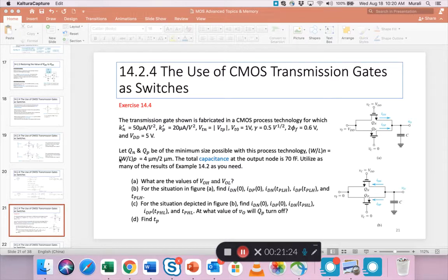All right. So here the one thing that has changed is that the output capacitance is now 70 instead of 50, which was previously the case, and that happens because now we got a PMOS device that adds a little bit of capacitance also.